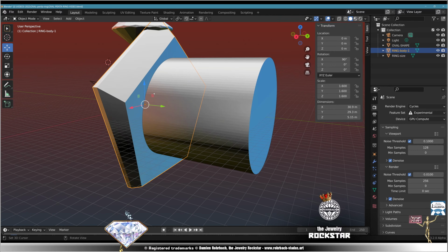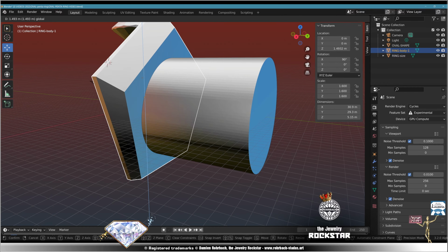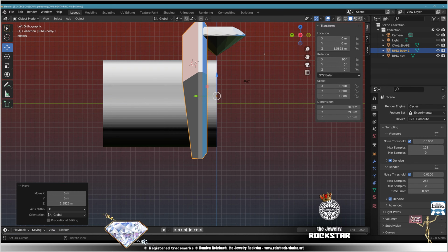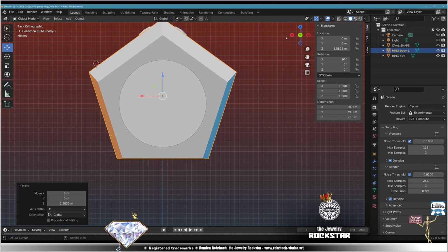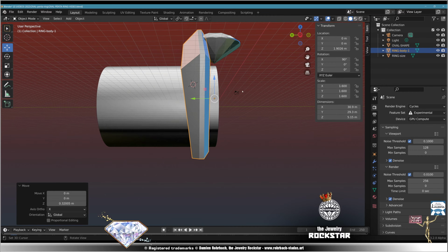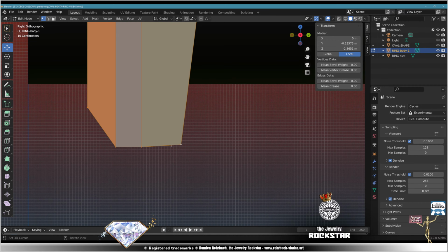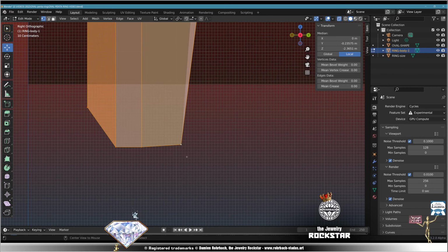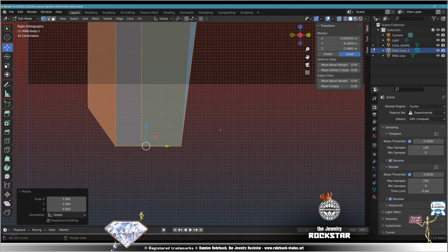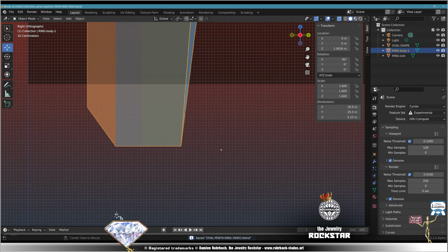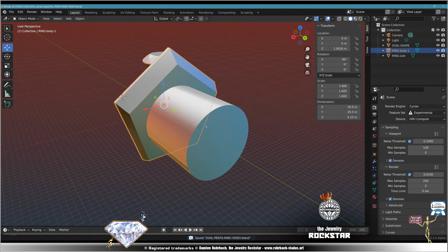Okay, great. Now it's time to center the body of the ring, so tweak it if necessary. Great, so now from the side view you can see that the bottom of the ring is not perfectly flat. So we're going to learn a small trick to correct that. Go to edit mode on the body of the ring, activate the transparency with Alt Z, and then select the bottom vertices with the B box selection. Now do a scale with the S key on the Z axis with Z and hit 0 to level up all the vertices. This is a very useful trick to even things out.